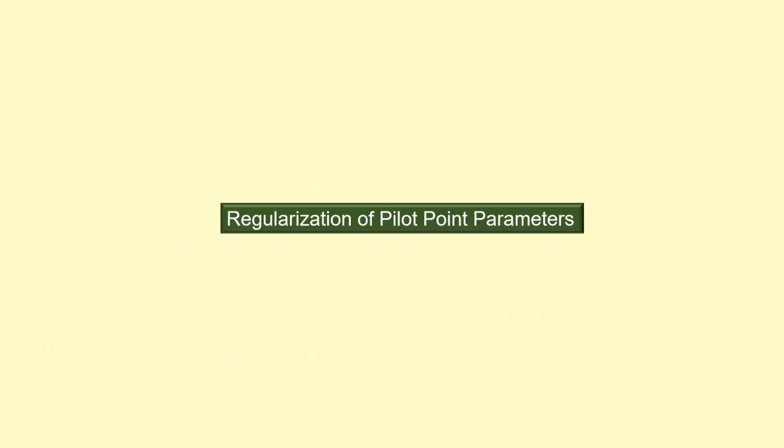So the next question is, how do we regularize our pilot point parameters? That is, how do we incorporate Tikhonov regularization into an inversion process in which parameterization is at least partially based on pilot points? There are a number of options that are available through the PEST utility support suite. We'll just talk about two.